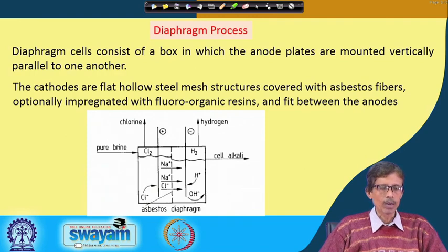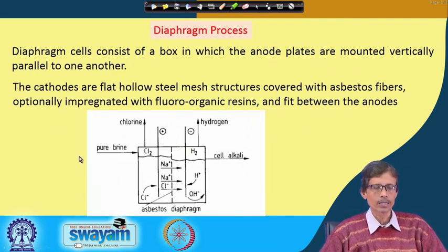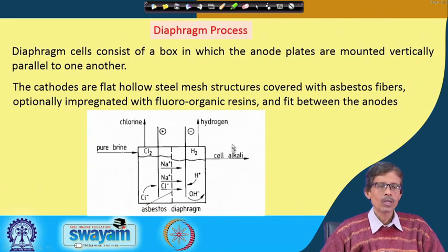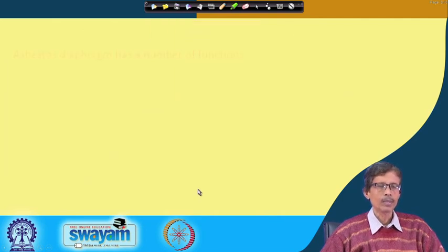During that process, simultaneously, there is no need to react the produced sodium amalgam separately, but you allow it to react together in the sodium chloride electrolysis. So, the diaphragm cell definitely has the advantage that together it will be producing two gaseous materials, and you have plenty of sodium ions and hydroxide ions within the reaction chamber. So, you have a saturated solution of sodium hydroxide within the cell.